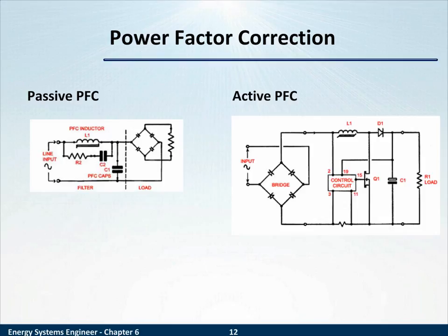For a design over 100 watts, the preferable type of PFC is called active power factor correction. With that said, and again reminding you that the electrical engineering behind power factor correction is beyond the scope of this certification, now is a good time to note that many electrical utilities penalize customers for poor power factor.